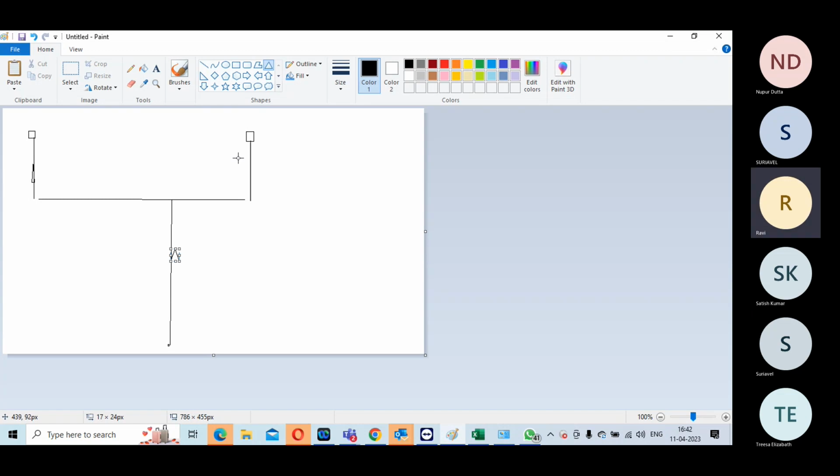You use exclude when you don't want to balance that clock pin with the rest of it. Yes, exclude pin is correct. You use a stop pin exception for the clock tree when you don't want the clock tree to be constructed after that. That means you have already constructed the other portion of it. So that is constructed, and I don't want your clock to build beyond that.